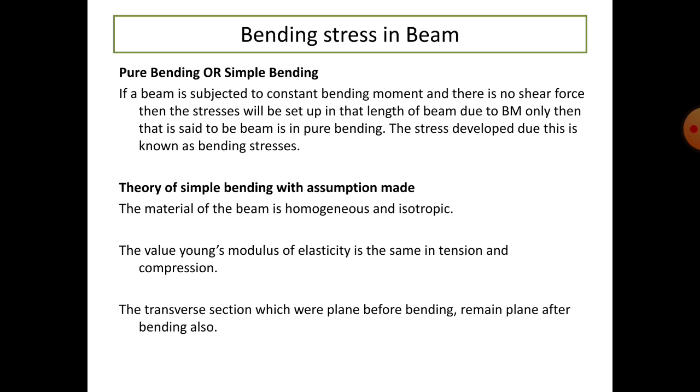Now what is pure bending? When a beam is loaded, and due to that loading there is no shear force, shear is not occurring at any point or any instance, and the bending moment due to the loading is constant, then that type of bending is called pure bending. There is no shear. Shear will be zero.